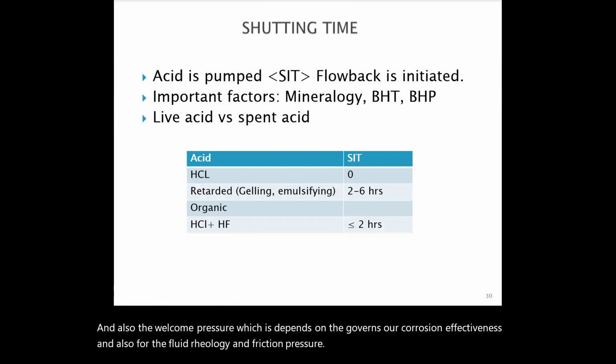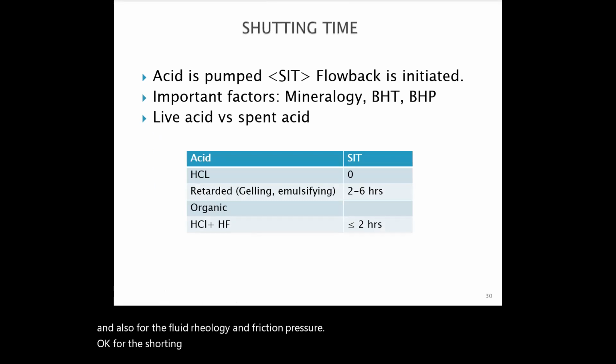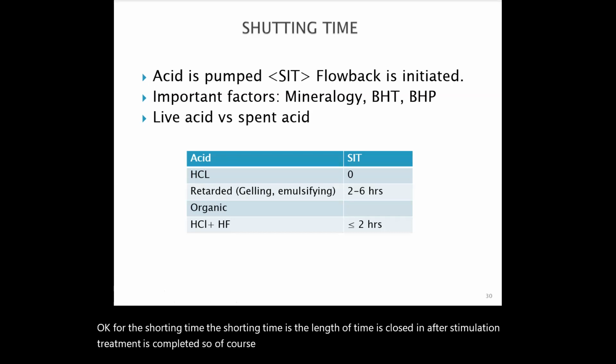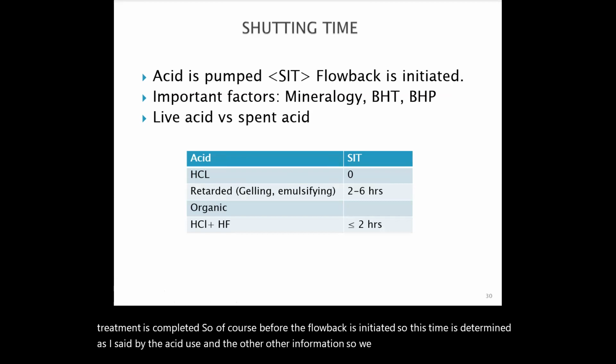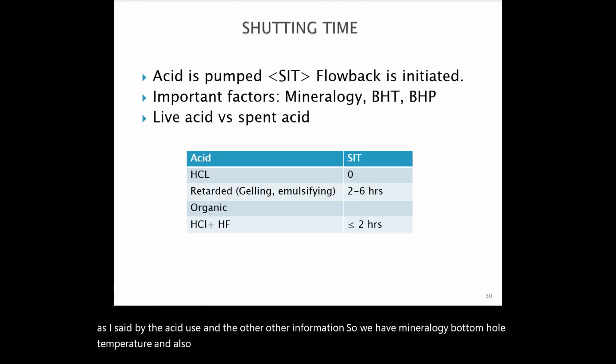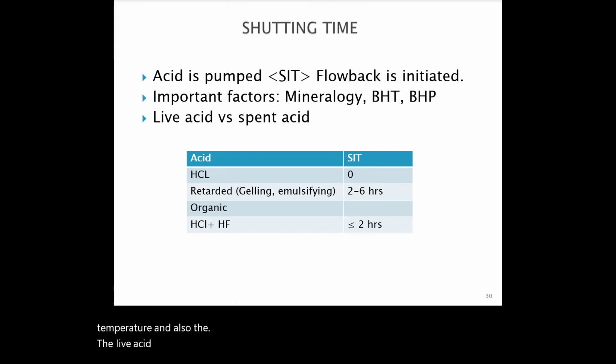Okay, the shut-in time is the length of time a well is closed in after the stimulation treatment is completed, of course before the flowback is initiated. This time is determined, as I said, by the acid used and other information: mineralogy, bottom hole temperature, and also the live acid versus spent acid. After a time, depending on the acid type, the acid will be spent.